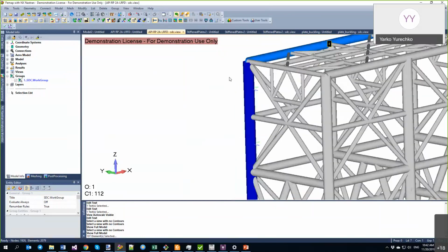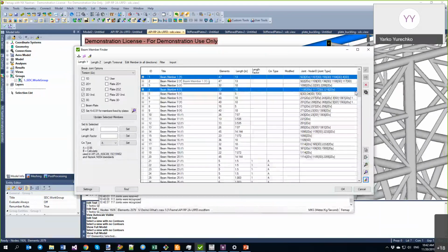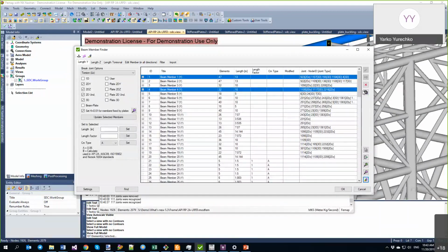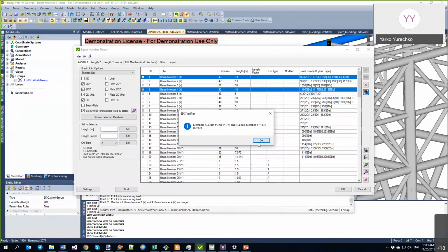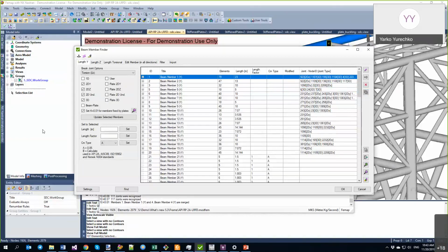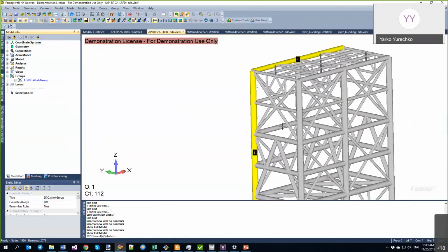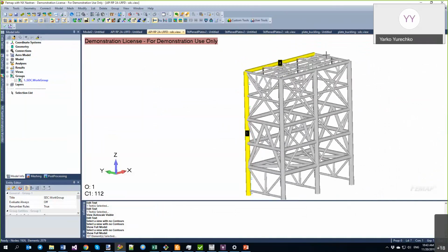And one last final option we have added. You can combine your members. It is possible only for members which have a common end. So here I have a common node. Completely different members are not possible. But if you press combine, it shows you members 1 and 4 are merged. And if I highlight this member, it shows me this member is now treated as one. It's not a very good example because you don't do that in reality, but they are neighbors, so it's possible to combine, and the length of the member will be the sum of those two lengths.